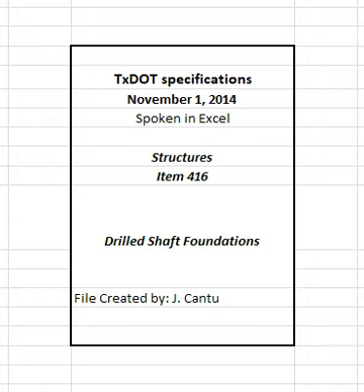Provide thermal analysis to show and temperature recording devices to verify maximum core temperature requirements are met as specified in Section 420.4.7.14, mass placements, as directed. Table 4. Maximum concrete placing temperature. See table in specifications. Form portions of drilled shaft that project above natural ground.